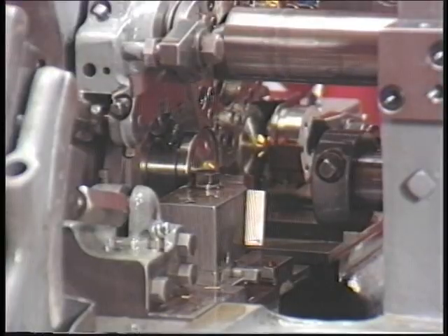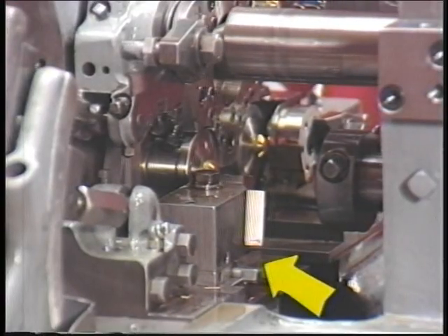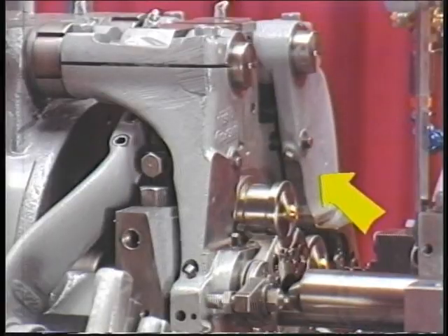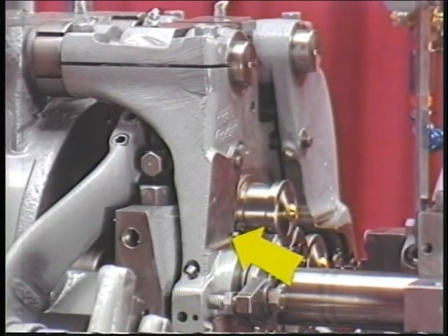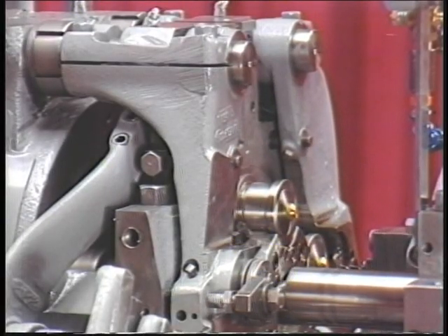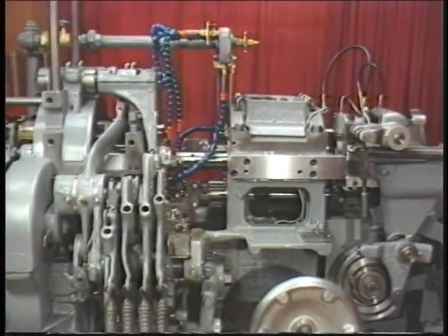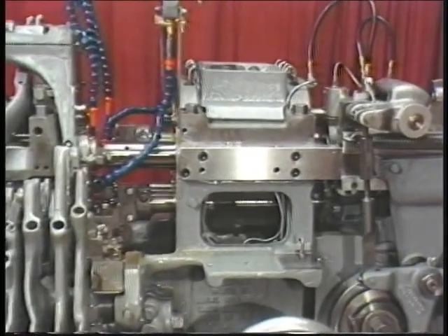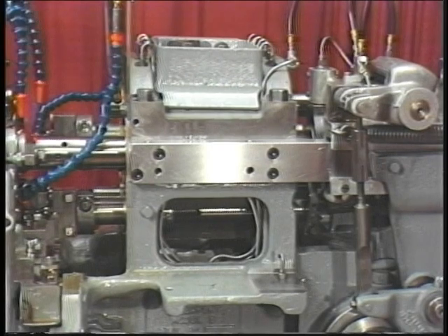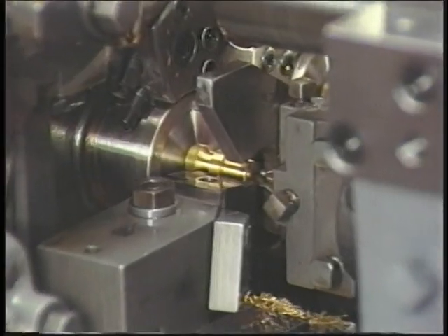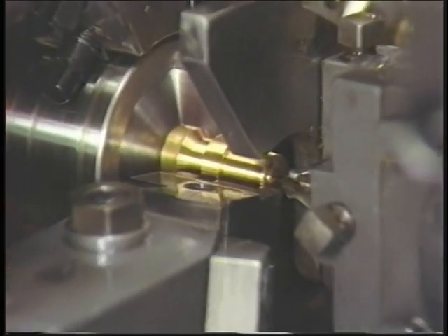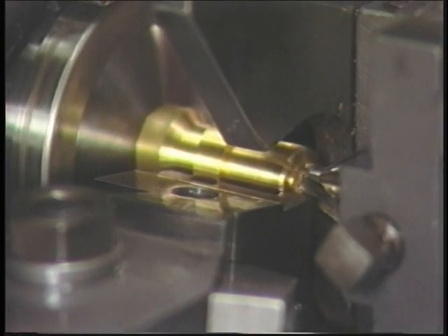Remember that the cross-working tools are mounted on the front slide, the rear slide, the rear tool arm, and the front tool arm. The end working tools are mounted on the tool spindles in the stationary head. Each of these tools performs a specific function on the bar stock in order to machine a finished workpiece.